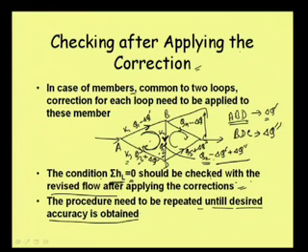So based on our total flow, or the approximate order of flow that we are getting, we should stop once our correction becomes significantly smaller and can no longer influence the revised value. Once our delta Q is very small, even if we apply the correction, the revised value will not change significantly. If we repeat, we will get the same order of correction and the revised value will just fluctuate. So we should not come to 0, but we should come to a desired accuracy level.